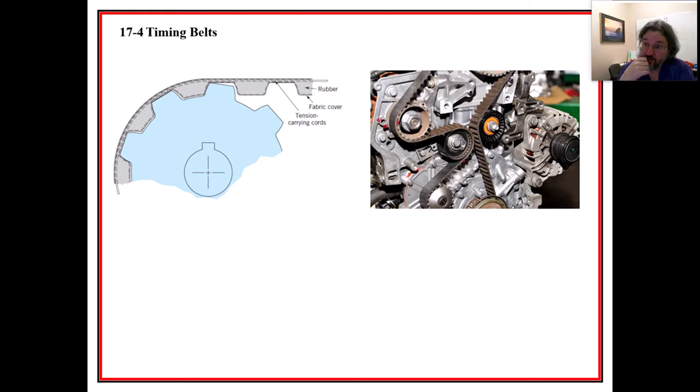that decides when ignition takes place, as opposed to a gasoline engine, which generally has either a carburetor or it can have fuel injection, mixing air and gasoline together outside of the cylinder, and then it comes into the cylinder and it does this explosion. But that timing in older engines was done with a belt.